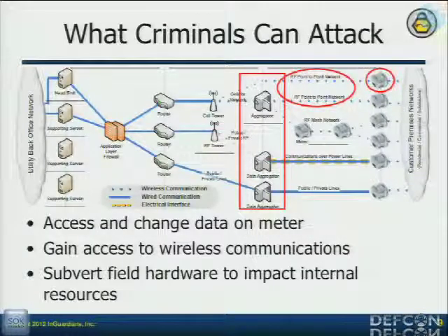So this is the basic breakdown of an AMI methodology. The stuff that's outlined in red, those are the publicly facing devices. The one on the far right is a smart meter. Now, smart meters can be meshed together. They either communicate over 900 megahertz, communicating with other meters and with the aggregators that are on the pole top,